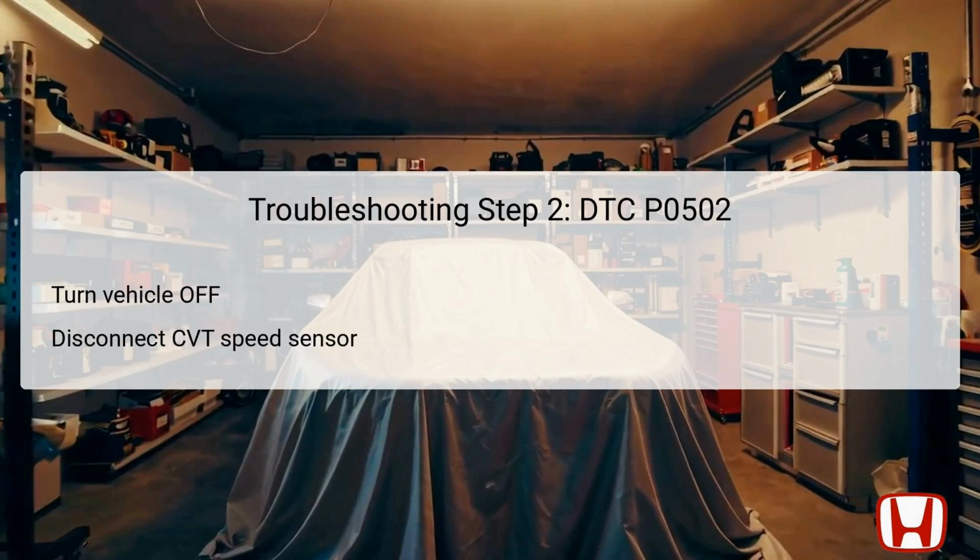In this second step of the troubleshooting process for DTC P0502, one must turn the vehicle to the off, lock mode. Upon safely positioning the vehicle, the next critical step involves disconnecting the CVT speed sensor by removing the 3P connector. This action isolates the sensor from the electrical system, allowing for precise testing of the wiring and connection integrity without interference. After disconnection, it's critical to proceed with electrical testing to identify voltage and continuity issues.